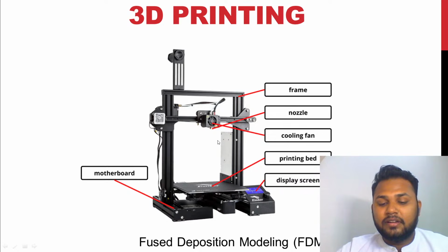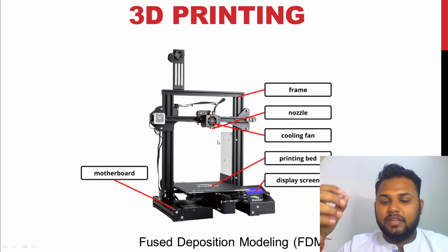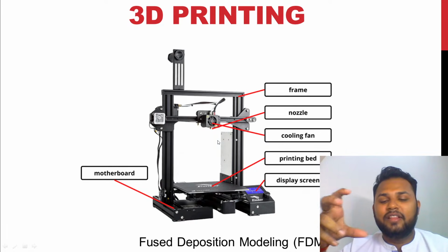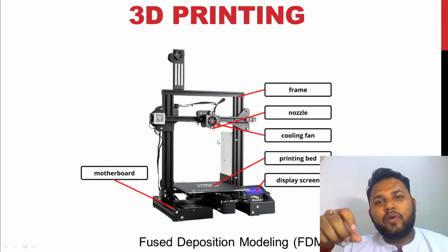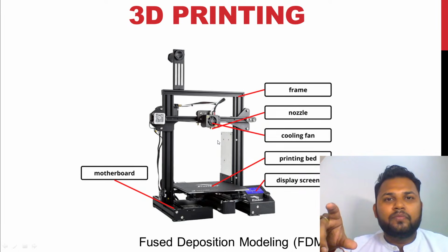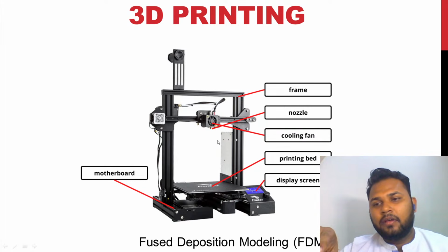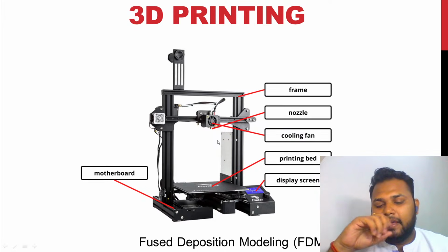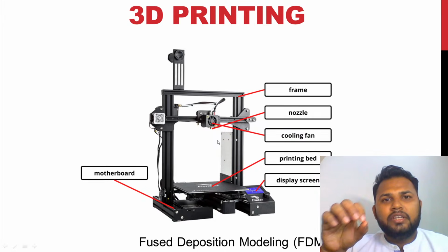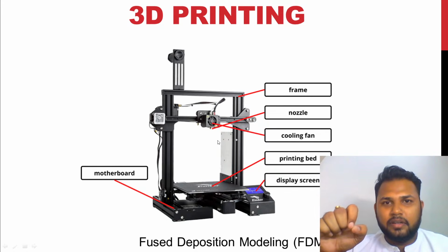So the right answer is that we can set it according to the situation. It is also a kind of myth that people think it requires a fixed temperature. When the material is completely new, the plastic wrap is unbroken and you have just pulled it out of the packing, initially you can start printing at 175 degrees centigrade.